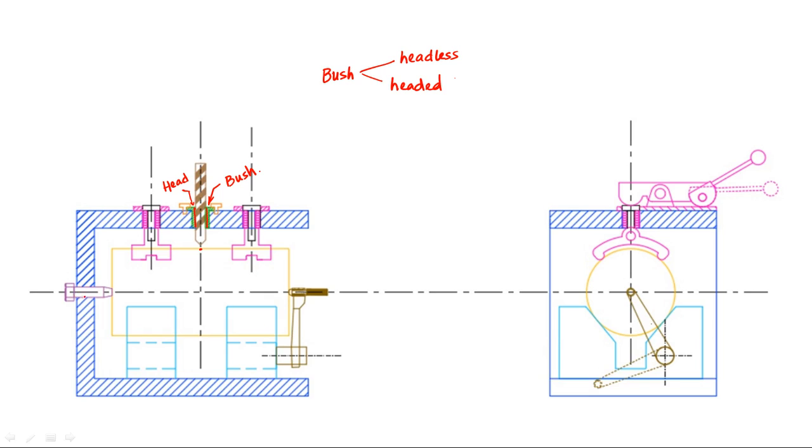And these locator pins are adjustable in nature, because if the axes are not aligned properly, then with the help of this locating pin we can move the object a little bit so that the alignment of the axes will match. Okay,